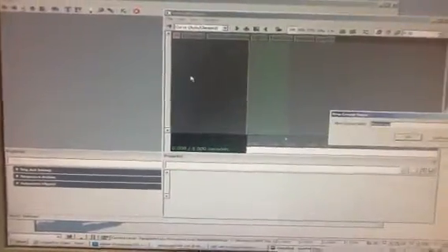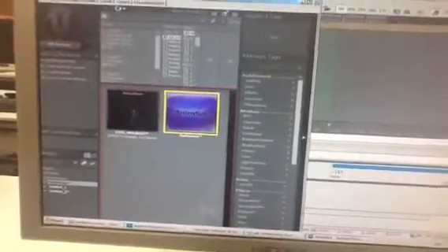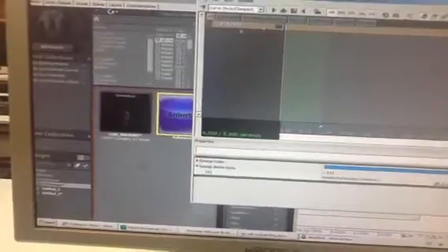Now we've got our skeletal mesh in the scene. Open Kismet, right click, new matinee. Now double click the matinee, and in this grey area here, right click, add new empty group. So you can give it a name, warp test. Now there's going to be some options which come up. So here I'll press the green add button, open the content browser and select the anim set, which is the part of the file with the animation in it,